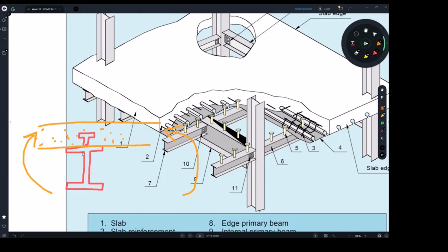Because if you remember, in the portal frame, one of the weaknesses we had with an I section is the top flange will get buckled when it's under compression, and that's why we need to lock it in with purlins, or use fly braces and all these kinds of techniques. But here, we're going to actually stabilize the top flange because it won't get buckled due to compression, and again, the strength is going to be way improved. So that's again a composite section.